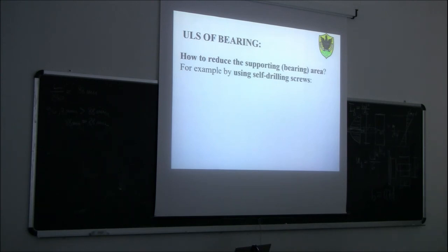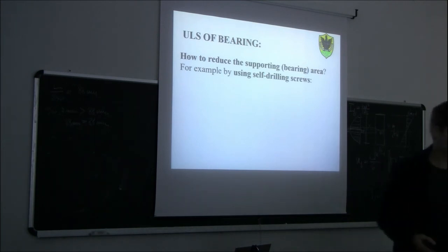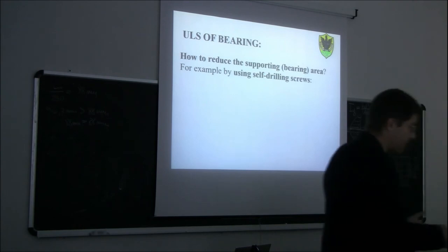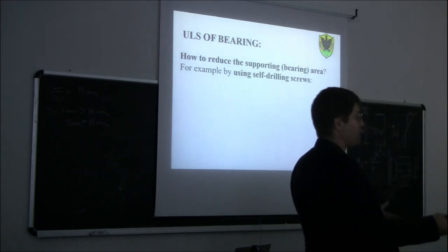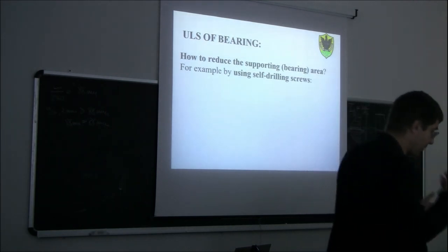It means that this beam must be supported by a column which is at least 66 centimeters wide. It may also be enough, I mean, it depends what you have underneath. But of course, if you are supporting this glulam beam by a column, the column would also be 66 centimeter by 18 centimeter.